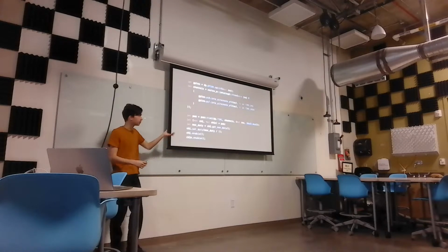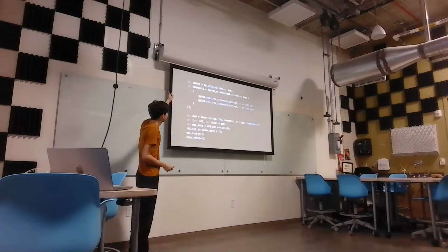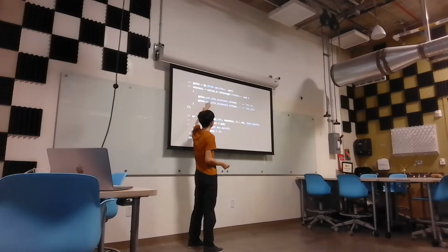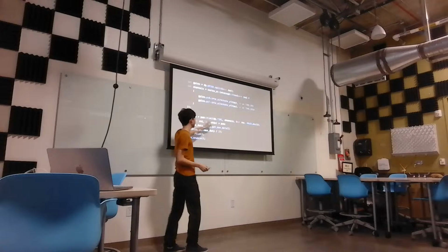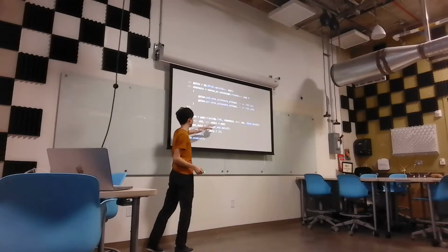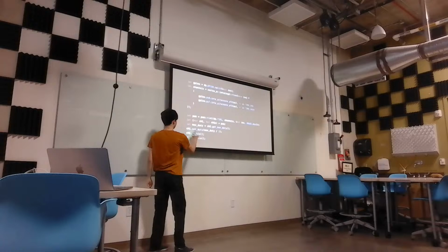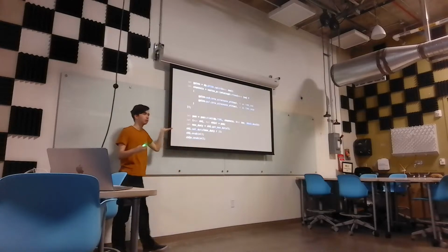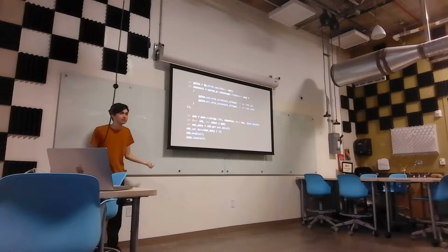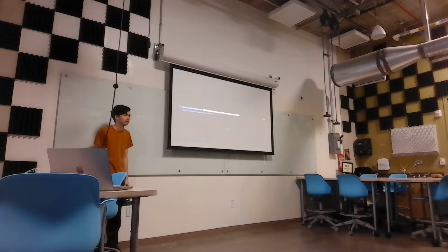Well, Rust has you covered. We have a HAL. And look, it's so easy to say, okay, here are my channels. I want them on P8, P7. Make PWM with those channels. Extract the channels from the PWM, set them, enable them. And it works. Here's the thing though. When I first got this HAL, they didn't support complementary PWM. So I had to add it to it. This is the first pull request of today.